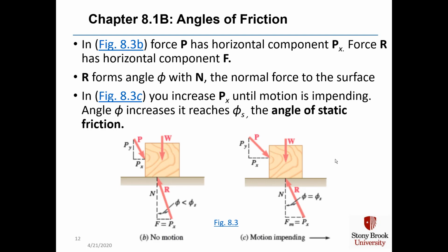Let's discuss angles of friction. In figure 8.3b in the lower left, force P has horizontal component P sub x, and force R has horizontal component F. R then forms an angle phi with N, which is vertical, and that's the normal force to the surface. In figure